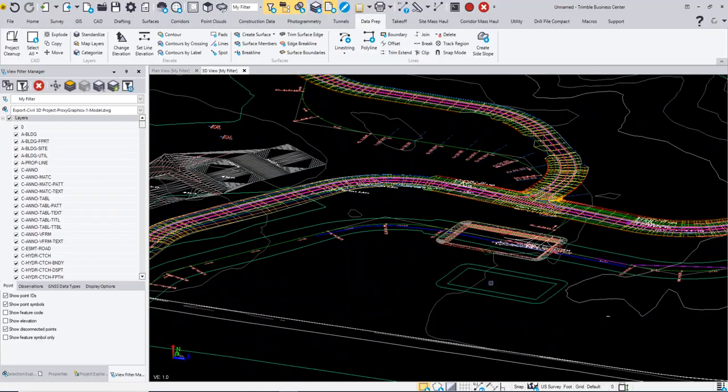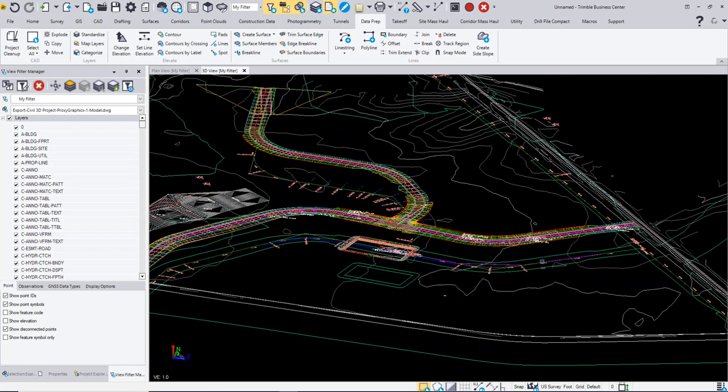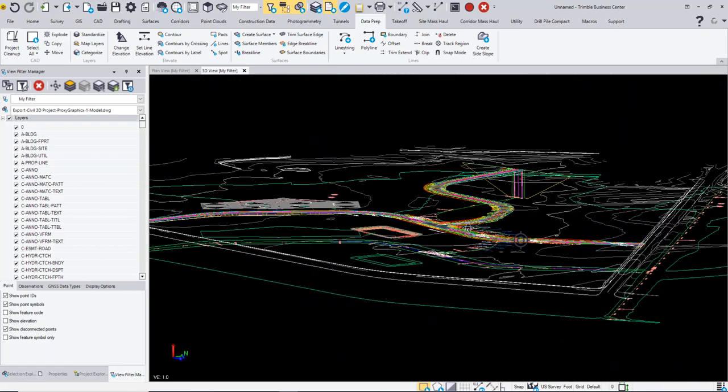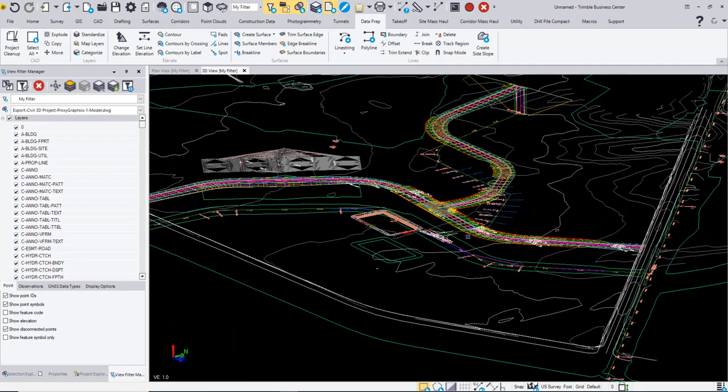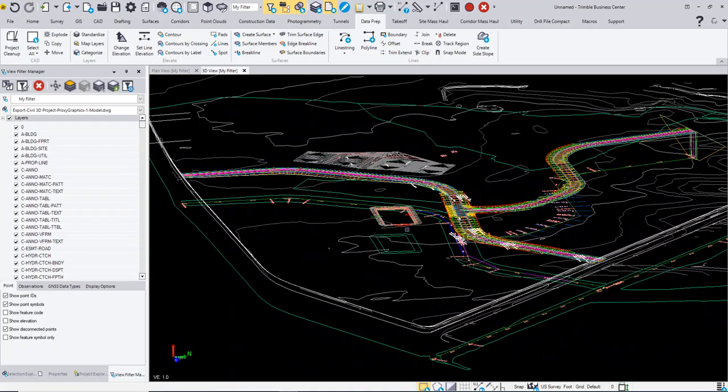You'll notice that some information is down here at 2D, so I do lose some. In this case, the boundary is down at 2D. Alignments in Civil 3D are all 2D, so the alignments are down here anyways. They're not going to be elevated, so you're going to have to elevate those as well. Again, this is just the CAD objects. What we want is actually a combination of the CAD objects and a LandXML file that's going to give us the design data, which we'll talk about in a follow-up video here. So again, have the Proxygraphics set to 1 regardless of whether you're saving it or exporting it.